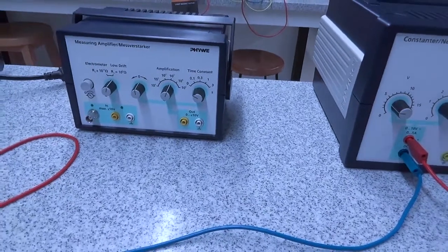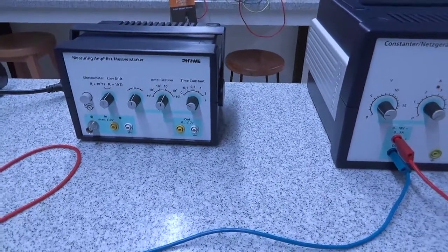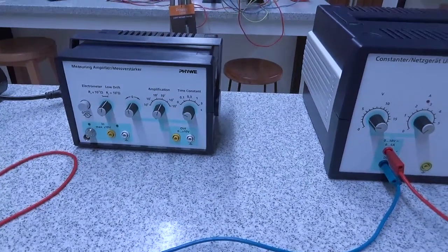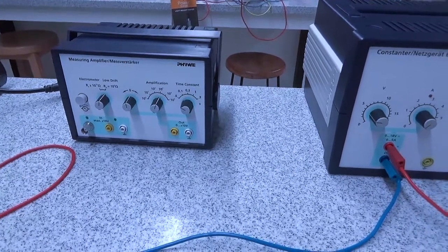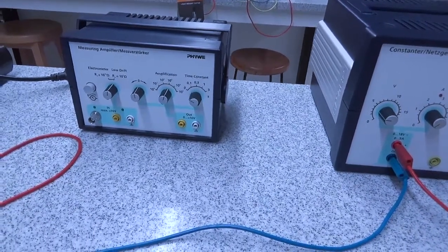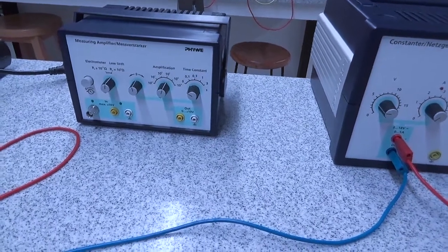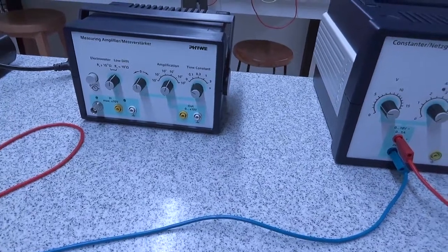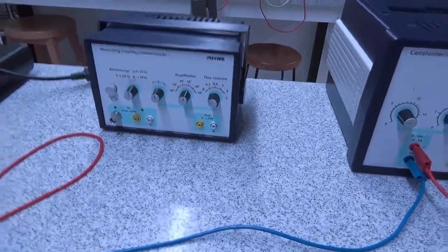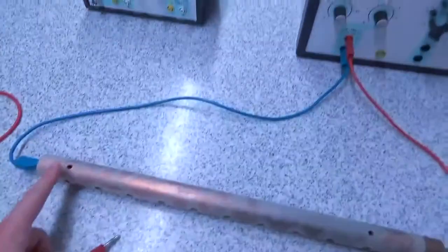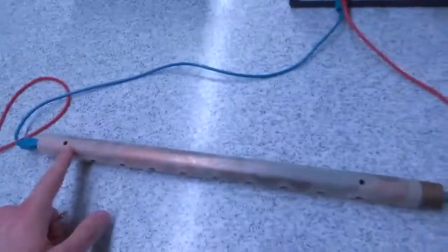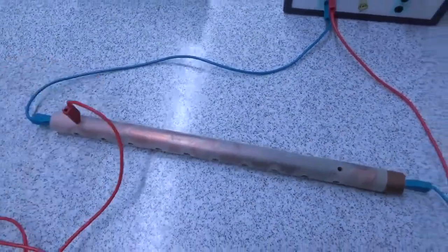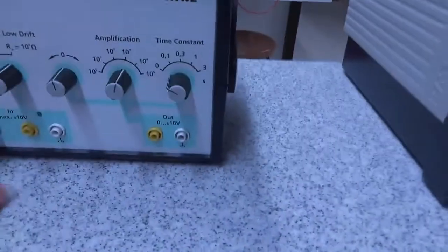So for example, if you are reading a certain value of 0.2 millivolt, and you are using a certain amplification of 10 to power 2, therefore that value of 0.2 millivolt would be multiplied by 100. So you would be magnifying it 100 times. So it's not like you are adding an external voltage to the already existing voltage, but rather you are magnifying the voltage that you are reading. So in that case, over here on that rod, as we can see, we have two different sockets or two different ports. We are going to bring one connection from the first socket, and we are going to plug it over here.